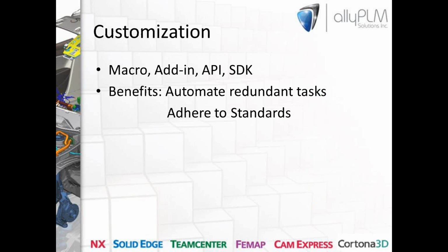When we talk about customization, it's going to fall into two broad categories. We talk about macros and we talk about add-ins. Some of you are familiar with these terms from other applications, even in the Microsoft Office suite, where you can create a macro to automate redundant tasks. A macro will typically be delivered as an EXE or a DLL file. It's going to run in its own process outside of the Solid Edge process.